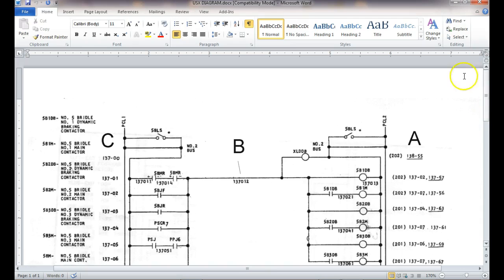So in Allen Bradley, when you're assigning a symbol, you're actually assigning a name to that symbol. And what's nice about symbol names is that once we assign a symbol name to a device, then instead of remembering that logical address, we can use the name, which is pretty neat. Everybody okay?